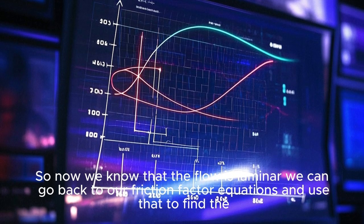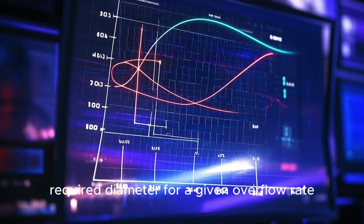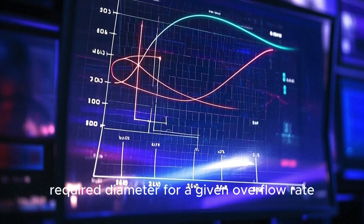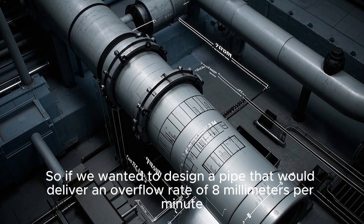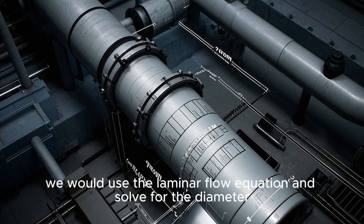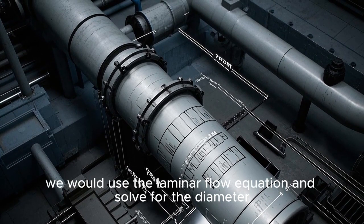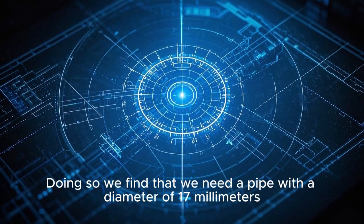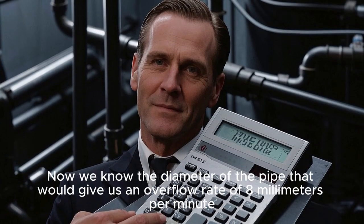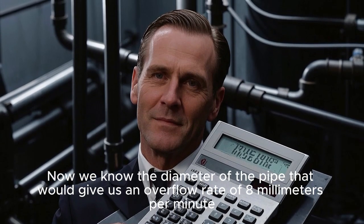So now we know that the flow is laminar. We can go back to our friction factor equations and use that to find the required diameter for a given overflow rate. So if we wanted to design a pipe that would deliver an overflow rate of 8 millimeters per minute, we would use the laminar flow equation and solve for the diameter. Doing so, we find that we need a pipe with a diameter of 17 millimeters.